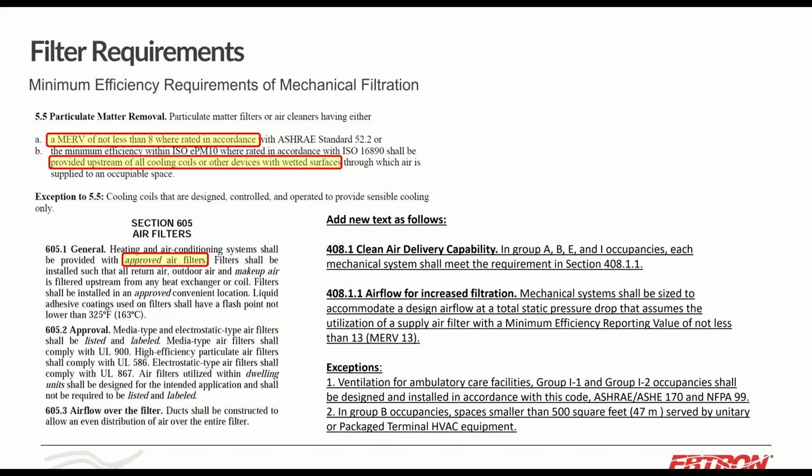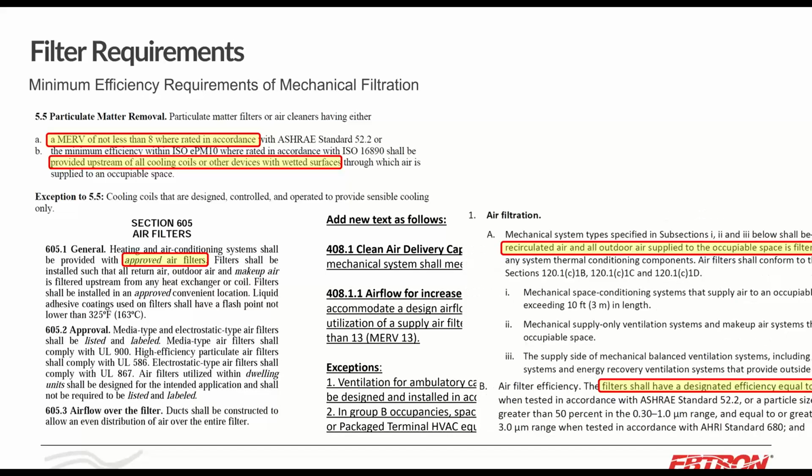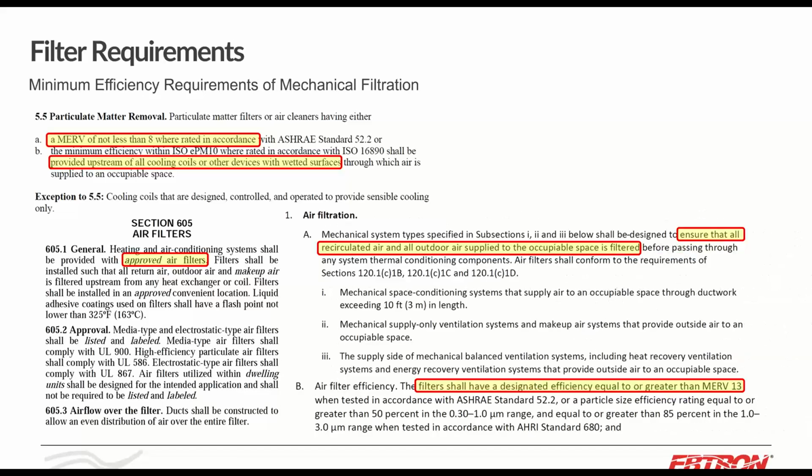having any requirement. But there is a basis for this, and in California, Title 24, they seem to really care about the health of the people inside the buildings. They're not only concerned about recirculating air in the space, but they're also concerned about the outside air being filtered through this filter. Because of course, there is some smog in California, and they've had a lot of wildfires too. So MERV 13 filters do a very good job of removing the particulate matter from wildfire smoke, smog, and of course, anything else that I showed in that chart that's in the very fine category.